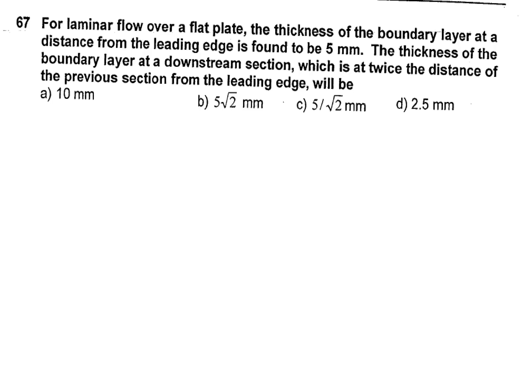Boundary layer delta by x equal to 5 by Re_x whole root. This formula we have to use for laminar flow. This one already mentioned, laminar flow.